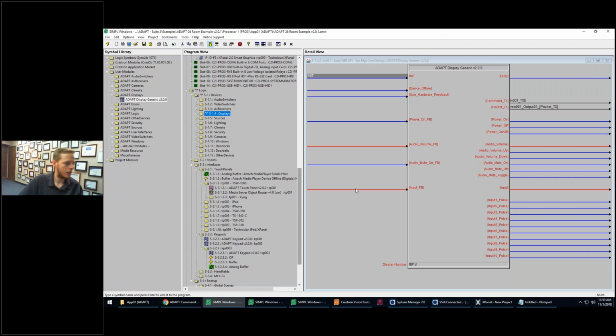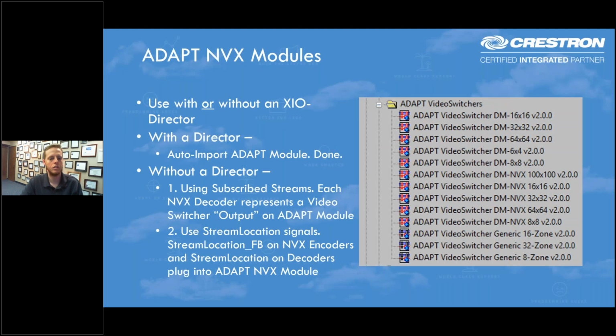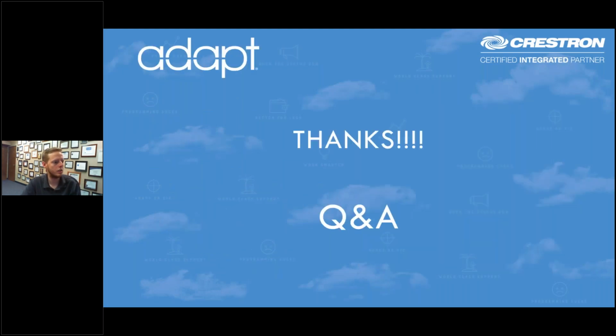Okay, so let me get my slide back up so everybody knows to ask some questions here. Another question I see in the chat is, with NVX and the XIO director, can you use method number 2 with the stream strings? Well, if you're using a director, there would really be no point in using the stream strings, at least not one that I can think of right now. If you are using a director, you're going to have all your traffic going through the director anyway, including your control traffic and your routing traffic, and so you may as well just use the auto-imported adapt module and use that functionality there.